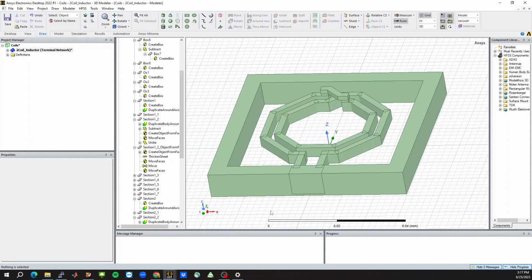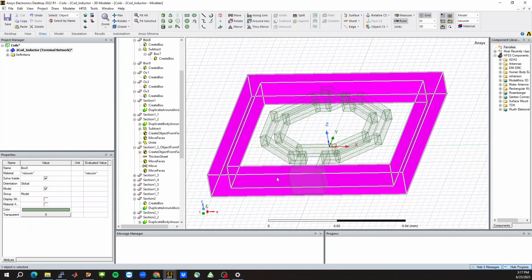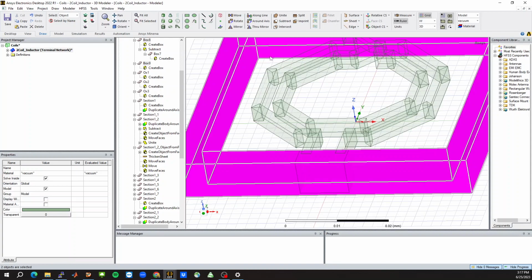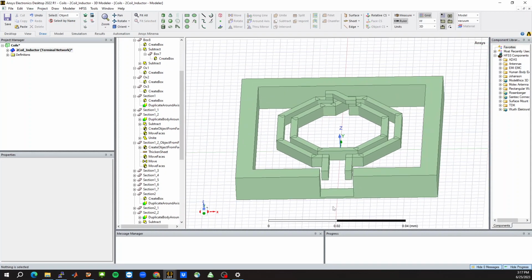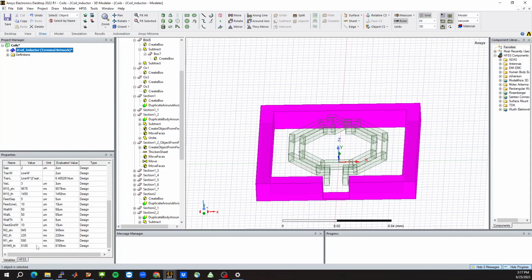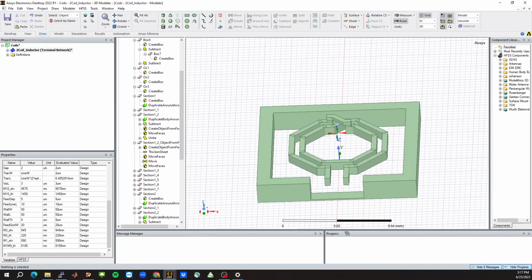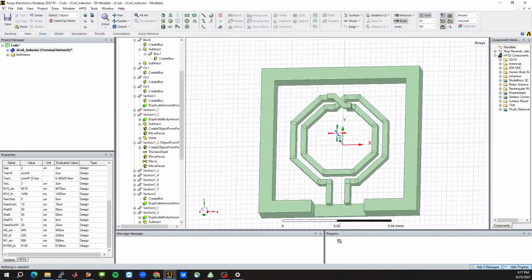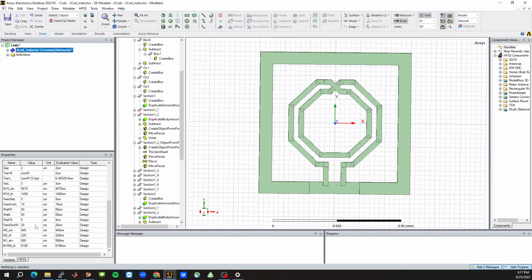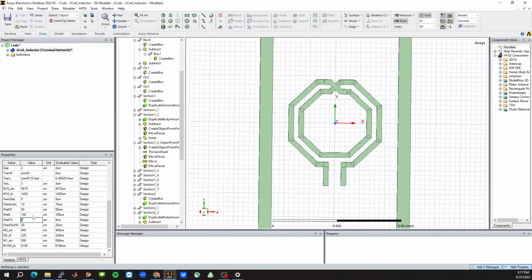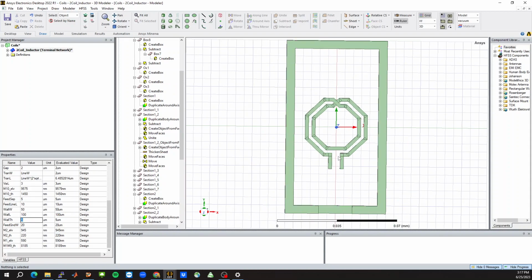Okay. So now we subtract this wall from the feed box. Subtract, done. Okay, feed ground width, let's make it 20. Okay, so that's what that looks like. There is an issue now. One issue is that if I change, for example, the wall width or the wall length, then the feed lines don't extend, but we do want that to happen.